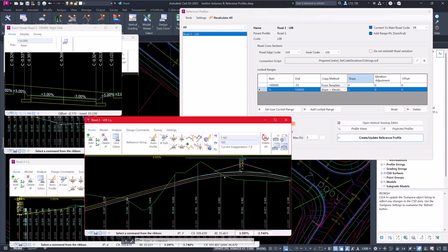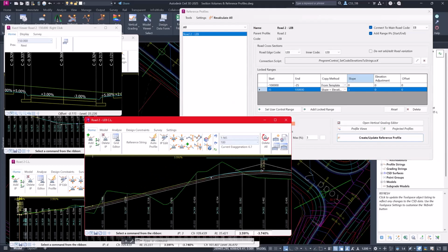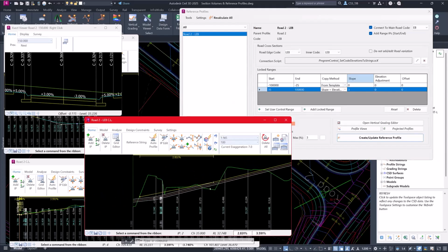Down the bottom here, the design that it's actually thrown is now essentially sitting on the top white line, which is the positive 3% projection from the design center line. So maybe that's a better solution. So I can start to muck around with the vertical design in here. So now I've got all the tools I want in terms of manipulation.